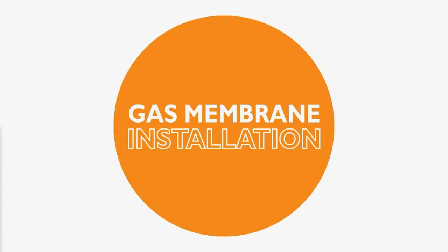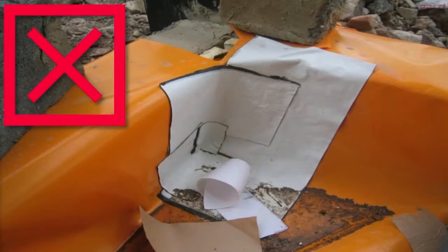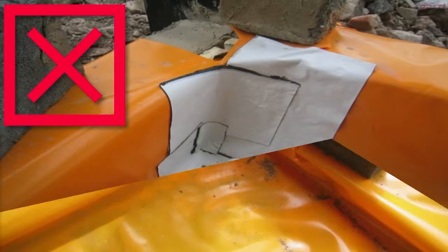We'll now move on to take a look at some common installation situations and the difficulties that can arise with each. We'll begin with corner details, which are probably the most common detail present on every site. This corner has been cut and resealed using flashing, but has been left unsealed at the corner. The membrane has also not been pushed into place properly, so any subsequent concrete or screed pours will overstress the membrane, which may lead to tearing and subsequent gas ingress.